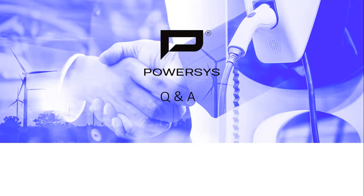Abhishek Shukla, you want to know about the transient thermal analysis of the IPM motor. Yeah, we will have a detailed session on how to carry out the transient thermal analysis of an IPM motor. Maybe in 3D, or else, as we discussed in the webinar, with the help of 2D we can carry out the transient analysis using speed priority mode, by which the equivalent thermal circuit is developed in a quick express mode, and you can see the temperature profiles of the different parts of the machine. That is possible. With that pre-knowledge, you can go for the detailed thermal analysis with the help of a 3D model too.